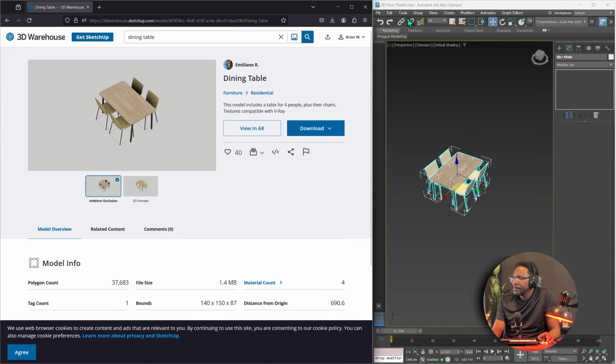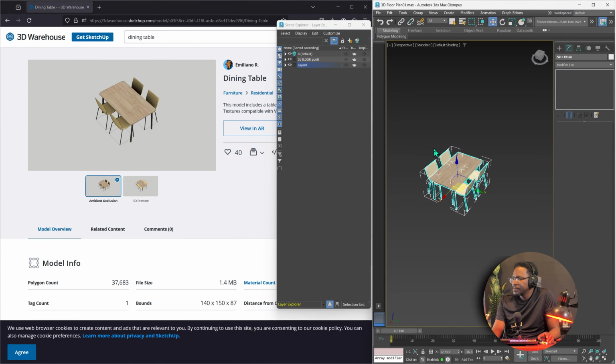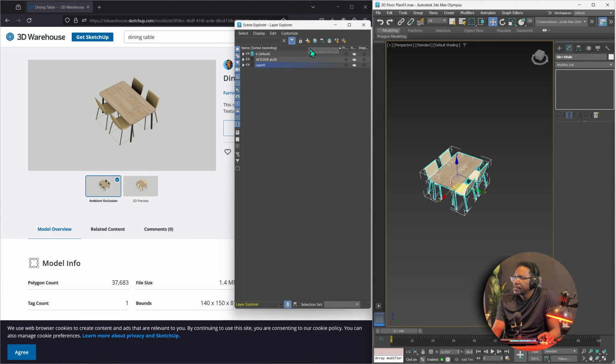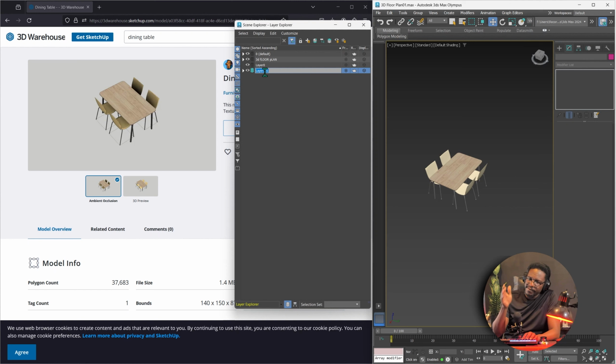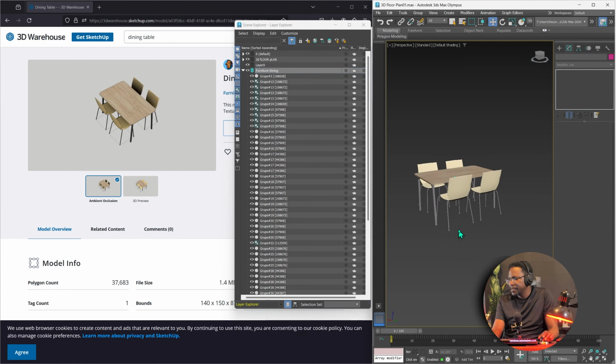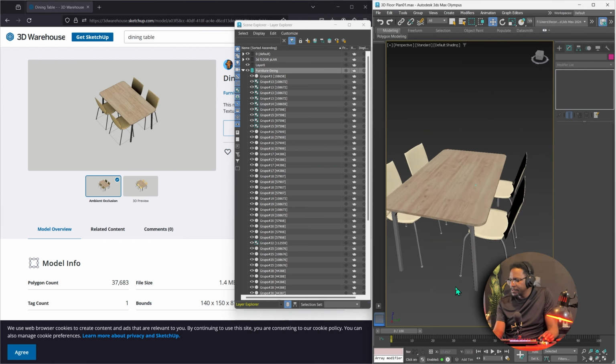And then what we're going to do is just put this on a layer. So while they're selected now, I'm going to just click this plus icon here. Let's make this a little bigger. So to create a new layer, I normally name my stuff starting from the broadest category and go down to more details. So for example, I'll call it furniture, then dash dining. There we go. So now this is on the dining layer as well. All right, this is great.